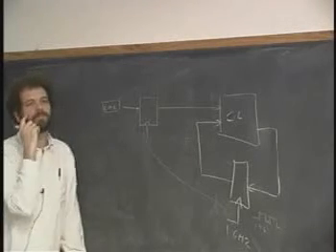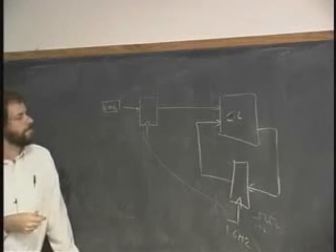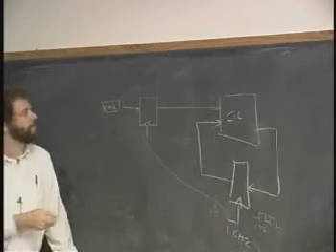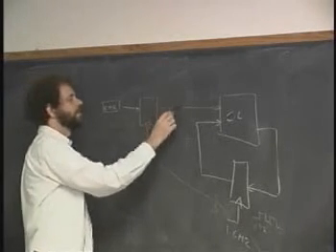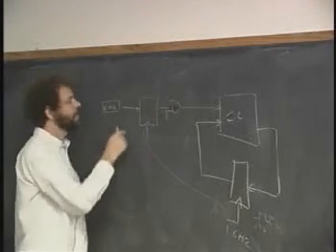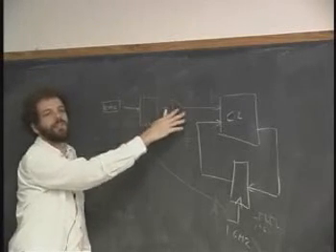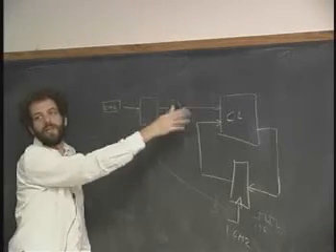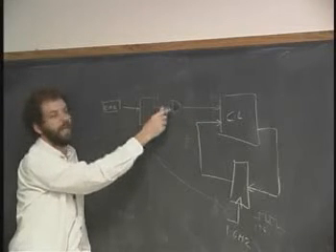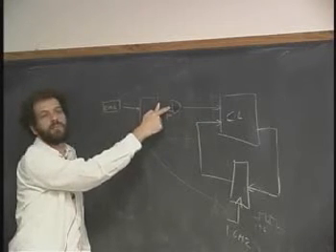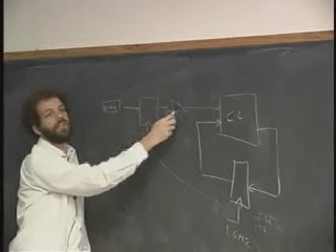So what do we do? Put a counter. It counts the clock cycles, and every 100 clock cycles, it sends off a tick. Yeah, that's possible. So we could gate this and say every time we want to look at the input, disable this for 100 clock cycles before we actually take the value. It turns out that AND gates are good at this. If this is a low, even halfway between a low and a high, this will still be a low.